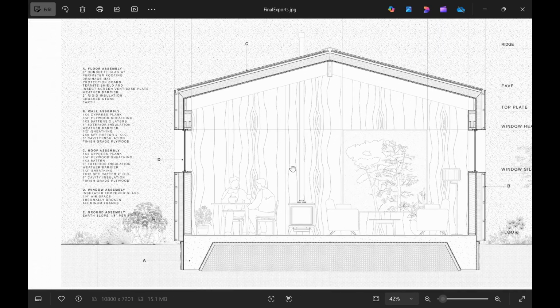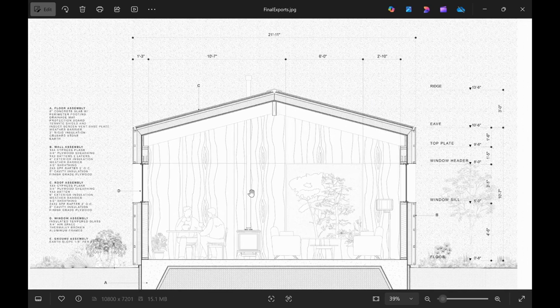And also, if you just look at the layout itself, like how I have things spaced off, I'm giving relief for the text on the left and the right, same thing with the annotations. You see, there's nothing crammed. Everything has space. Dimensions are pulled off completely. Some people don't like to do this. Some people like to have the elevation markers touch the actual elements it's referring to. I just like to give some space, okay?